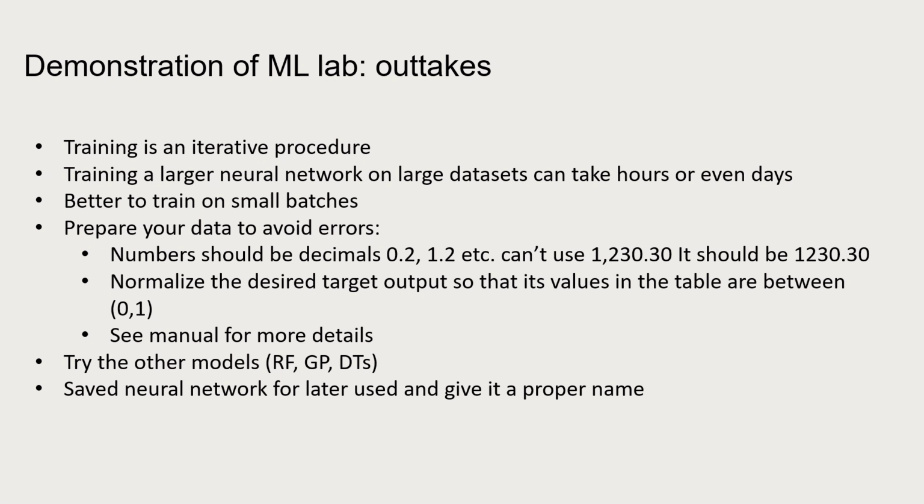And you need to prepare your data. Numbers should always be decimals. Do not use a comma in your data. It should always be in this format and should always be normalized, no negatives. And you can see the manual for more details on how to prepare your data.